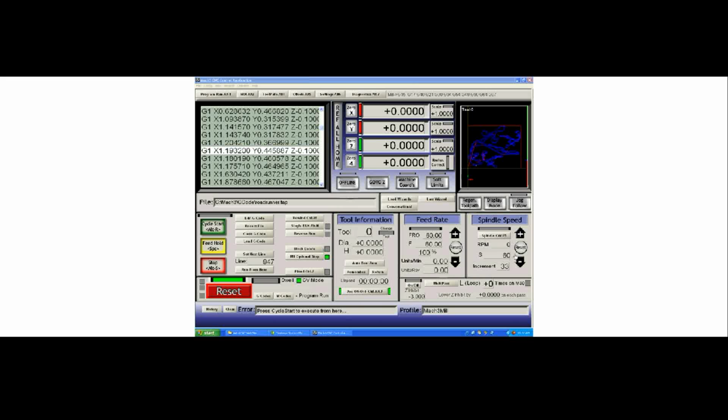Here we have our spindle speed selection. We can turn a spindle on or off. We have spindle speed override, that we can use to override the spindle speed that was set in the G-code program and allow the spindle to speed up or slow down. Pressing reset will of course bring it back to 0.